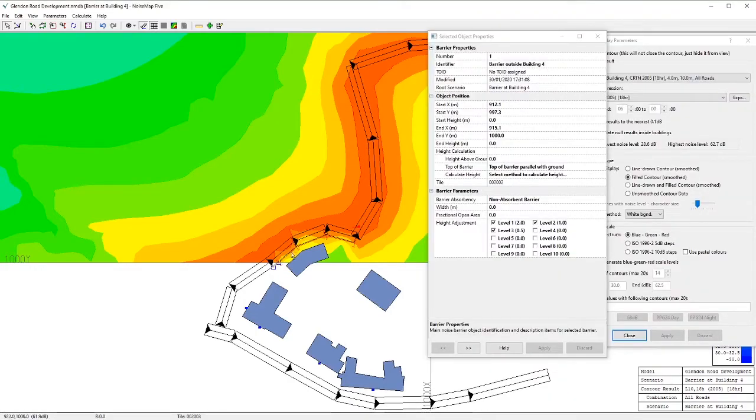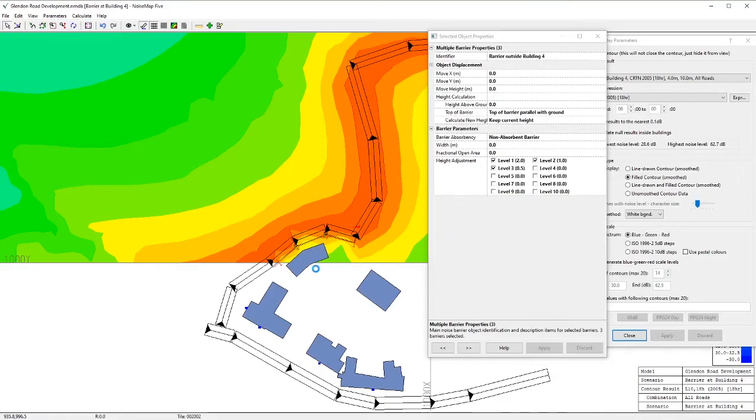If I select one of the barriers, press Ctrl R, then the whole of that chain is selected, but this end one needs to be selected because the chain breaks at the tile boundary. So I press the Shift key and click on it. Now all 4 barriers are selected. So what should we do? Take half a meter off the barrier perhaps. Okay, so I've unticked that and apply that to all the barriers. So they're now only 3 meters high.